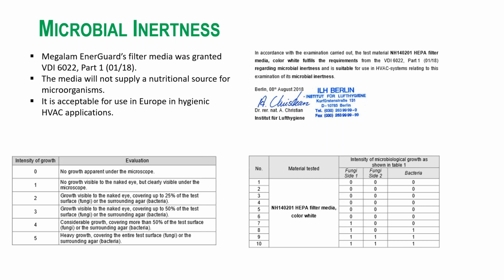Over the years, a couple of companies have introduced antimicrobial layers into their filtration media, usually an ionized silver or an ionized copper, to try to encourage the breakdown of cell layers in the bacterium. We've never been able to demonstrate that that's effective, and ASHRAE has a whole case study. If you're bored on a Friday night and don't have anything to do, I'd recommend you look it up, because it's a really good study which explains that HEPA filters, even sprayed with these antimicrobial agents, really don't have an effect on the long-term growth of microbials on filtration media. So it's definitely worth investigating.